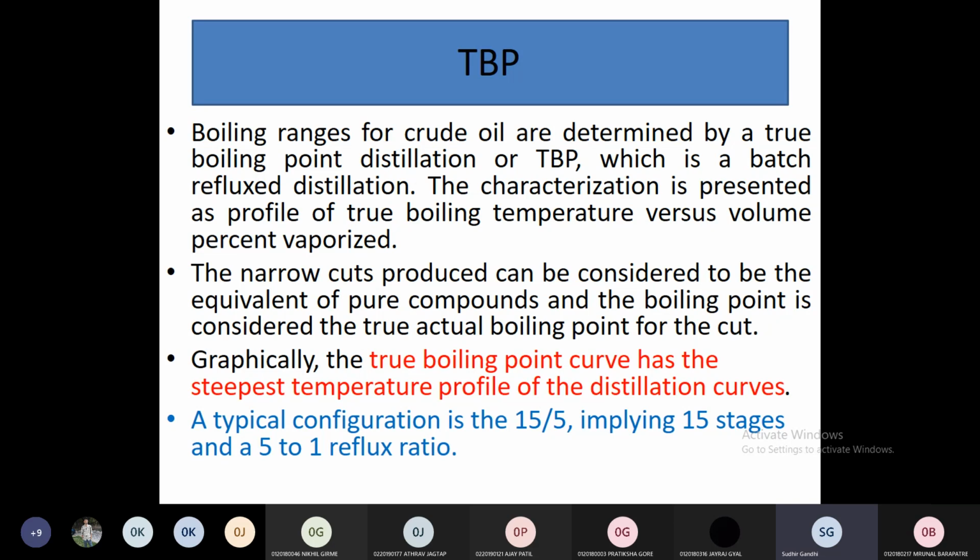Data to data, and that is due to the absence of packings in ASTM distillation. So there are no stages provided, and we are not talking about a reflux arrangement as well. That's why a more elaborated curve is not obtained, and the accuracy of ASTM distillation is comparatively less. But still, for the case of final products, it is a widely used, accepted